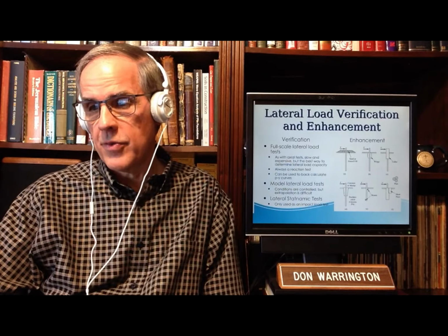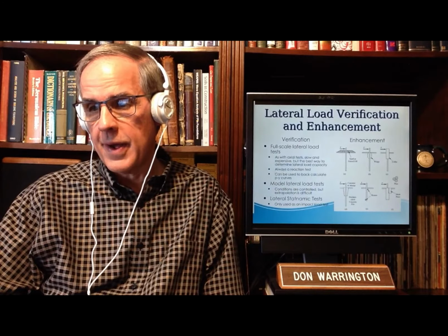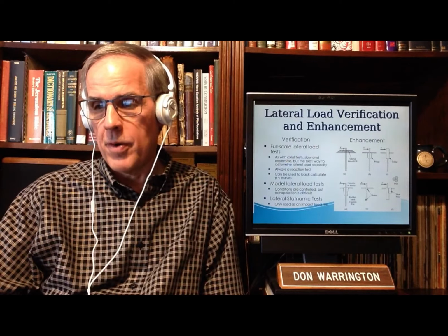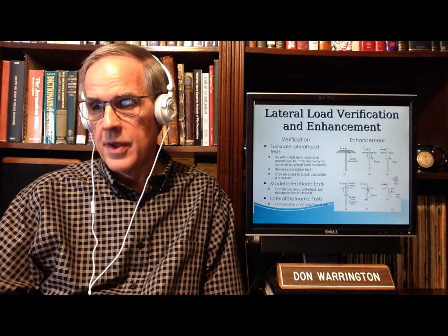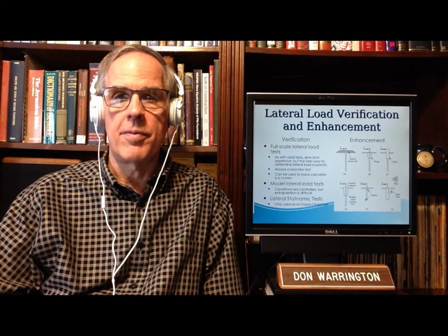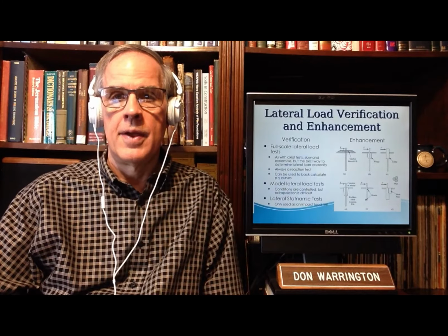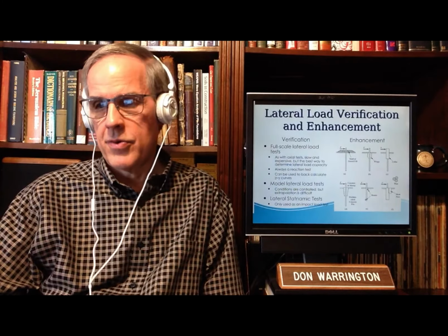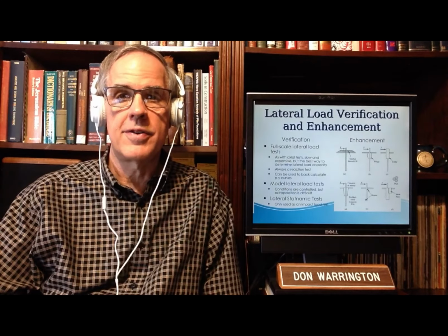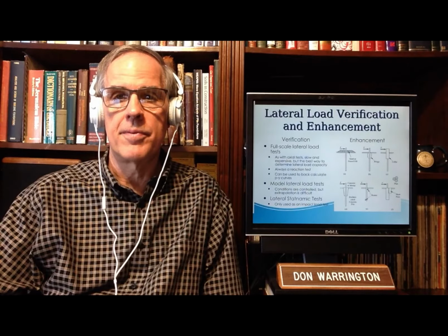Enhancement, there's all kinds of ways to do it. You can put fins on the pile. You can put a berm to back it up, sheet piles. There are a number of ways of enhancing the lateral load capability of a pile. And of course, one thing you can do, obviously, is make it bigger. And particularly in seismic work, that's the way we do it.